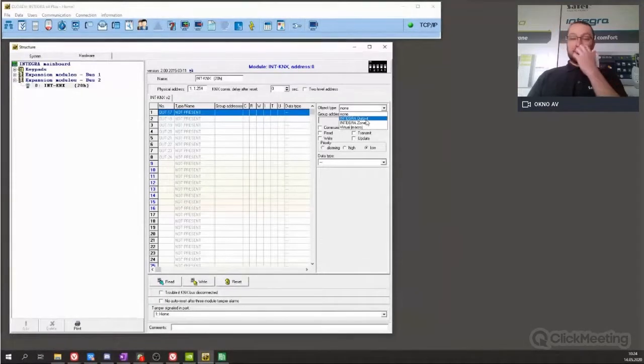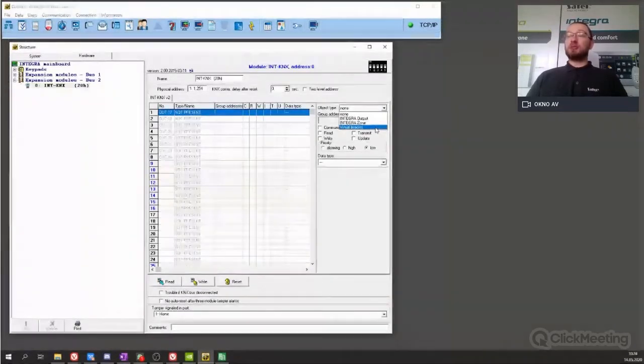You can treat information from the KNX the same as you use detectors in the system. They gather information from the room and send it to the panel. So this is an input or zone in this case. And virtual macro, you can also treat as an output, because you are using macros inside INTEGRA control or a keypad like INT-TSI to be able to control something in the KNX. But we make it separate because you will see later on that you can do many different things. You can combine many macros into one object macro, and this will give you a possibility.